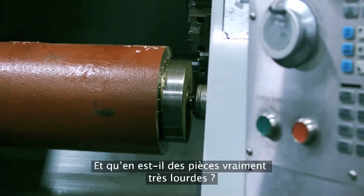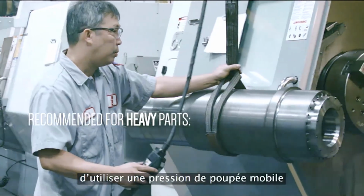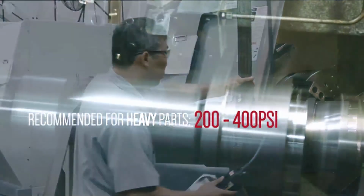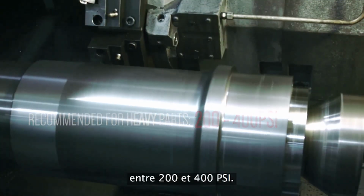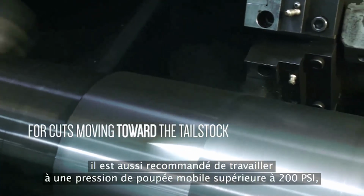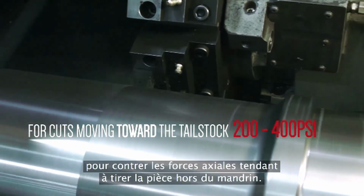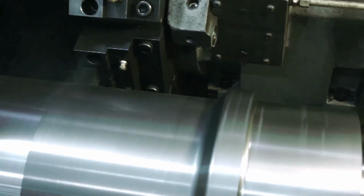And how about really heavy parts? When your part is very heavy, it does make sense to use tailstock pressures between 200 and 400 psi. And when you have cuts that are moving towards the tailstock, it's also a good time to consider running at a tailstock pressure above 200 psi to counter the axial forces that want to pull the part out of the chuck.